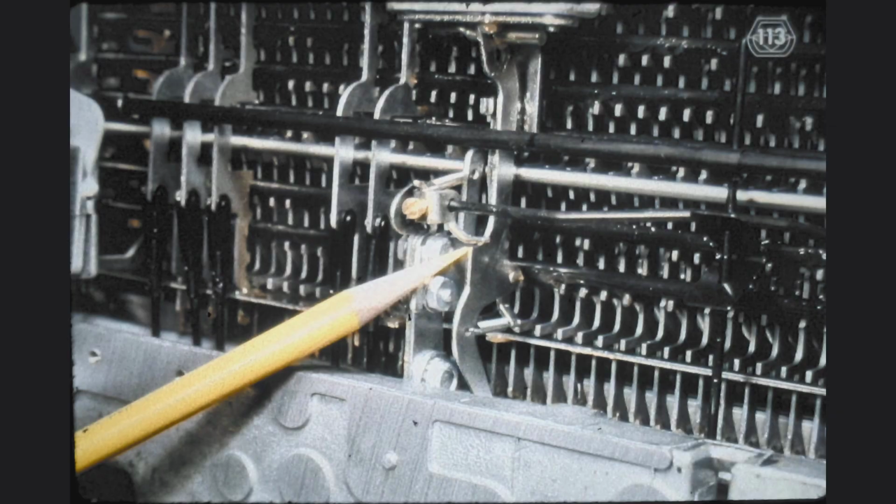If you examine the shift cam detent, you will find that the front end of the shift cam detent operates this character interrupter mechanism, so that at the step indicated, it prevents the rearward movement of the cycle clutch latch link. Thus, the engagement of the cycle clutch is prevented for as long as the shift mechanism is in operation. There are two adjustments to consider in connection with the character interrupter. First, the front-to-rear position of the lug, and second, the angular position of the lug.